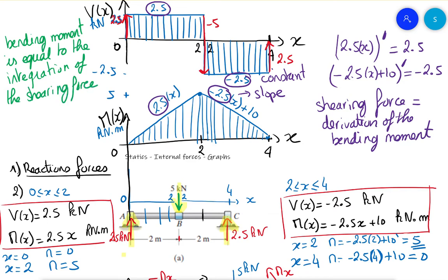Okay, when the moment is increasing, the shearing force is positive. When the moment is decreasing, the shearing force is negative.